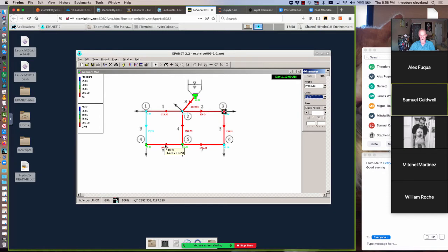So there's a property called reverse. And so we can reverse the connectivity. The moment I touch that, I just made it wrong, and it's been indicated by this has turned to a black marker. Let me rerun the simulation. And now we get it as showing flow coming out.